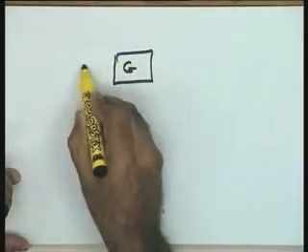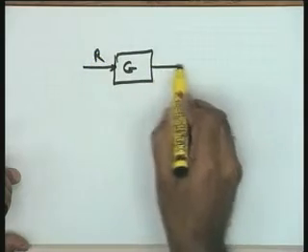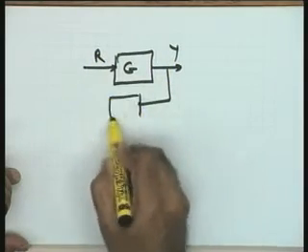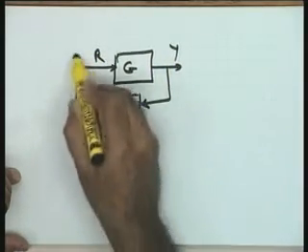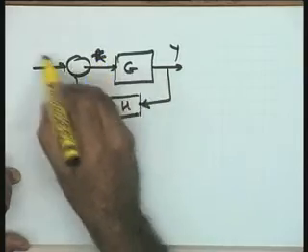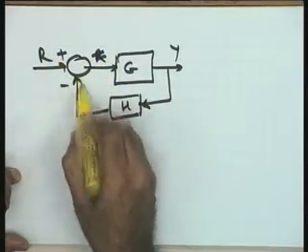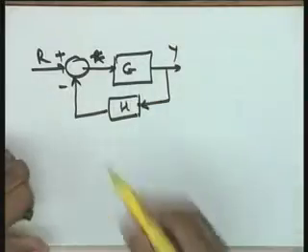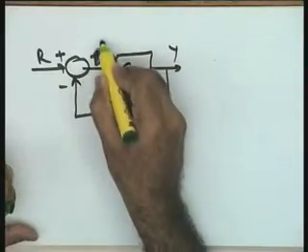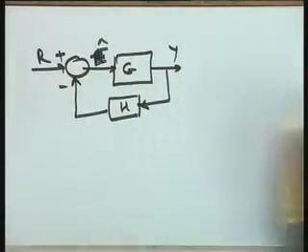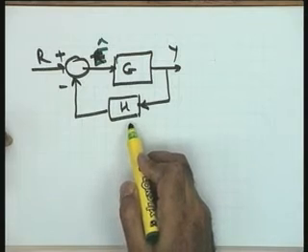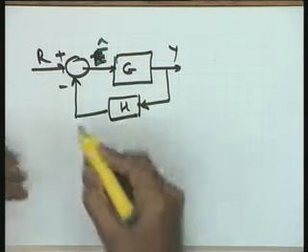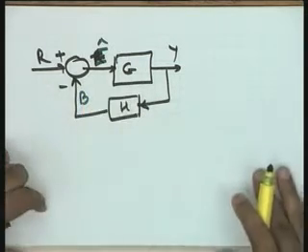Okay. Let me take a little more difficult situation, a feedback loop, R, Y through an H. I take a summing point here, let me take R here please, plus minus. Now, you give me the corresponding signal flow graph for this. Let me say that this variable is E cap. Now, the variable should be well set. I am taking E cap because there is an H, otherwise I would have taken E. The feedback variable let me take as B.